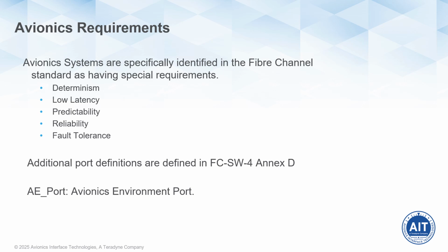Whereas in a commercial environment, everything's typically plug and play, and they're going to use self-discovery protocols. So they can power up and, not knowing anything about the network, define the entire network. But avionics systems are totally static, well-known, fixed configurations. And those plug and play protocols are fairly sophisticated, and they generally add unnecessary overhead to an avionics environment fabric. So for the AE fabric, we're just going to eliminate those protocols.